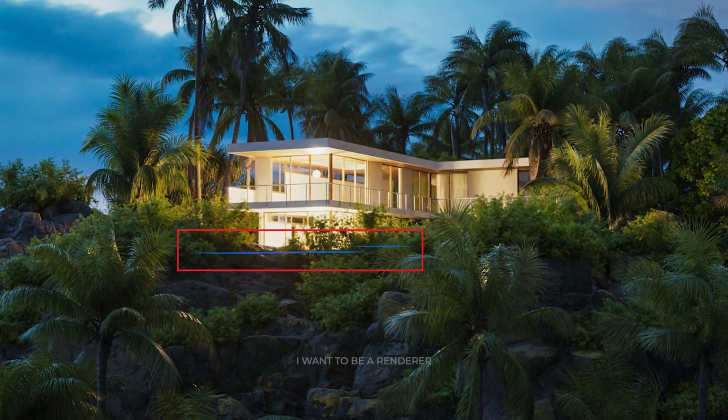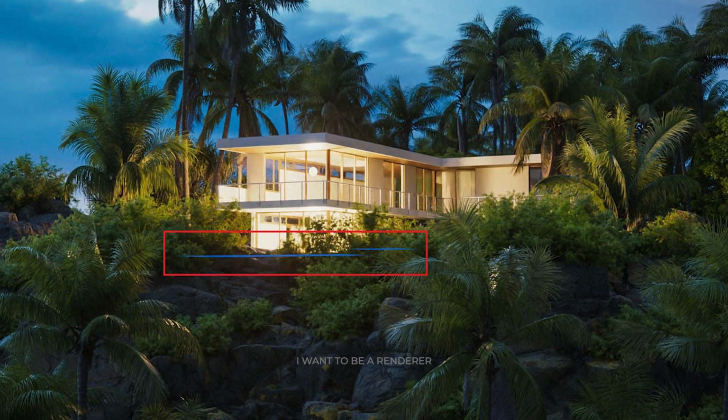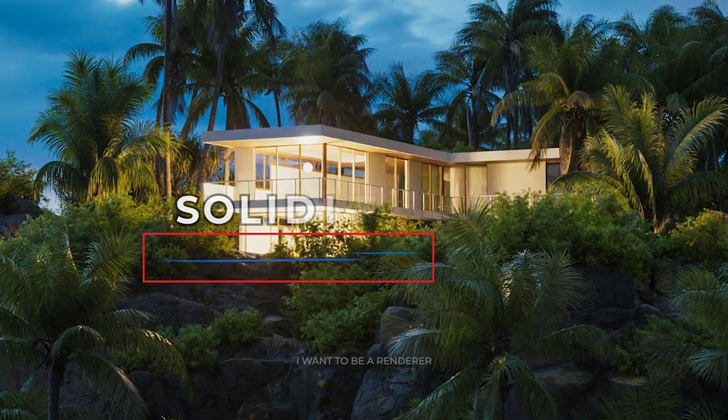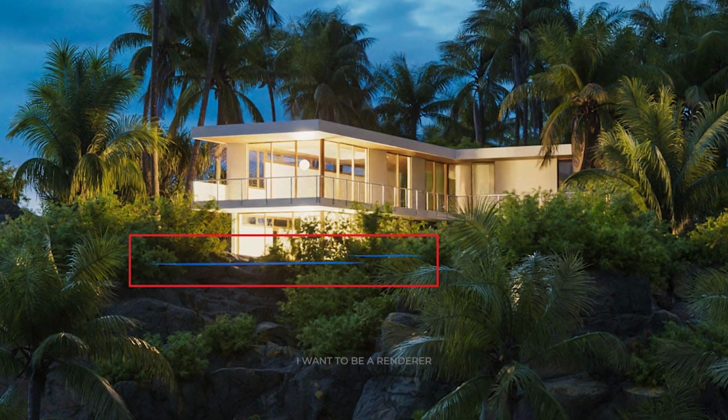Such a volume setting should also work well on any other body of water, such as pools, where he copied and pasted it. Finally, it is essential to give the object a real volume using the solidify modifier, or else it will not display correctly as we observe in this image.